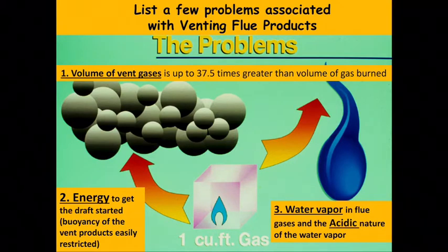The other issue is the water vapor. The water vapor in those flue gases is fairly acidic, and a lot of times tests have shown anywhere from a 2 to about a 5 as far as the acidic nature of that.